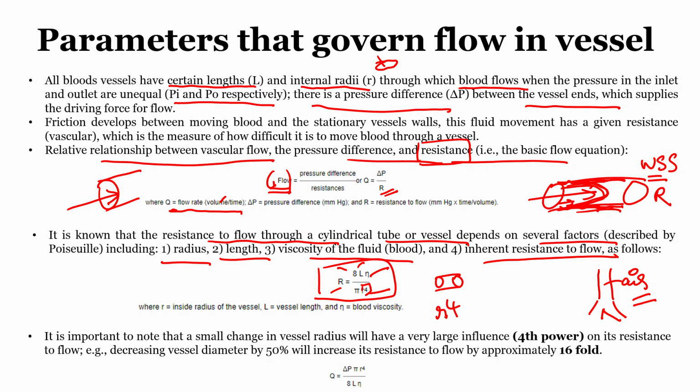This plays an important role because the parameter, that is the Reynolds number, talks about the fluid flow through a channel. The fluid can be laminar, that is there is no disturbance in the channel, and the Reynolds number corresponding to a laminar flow would be something less than 2000.